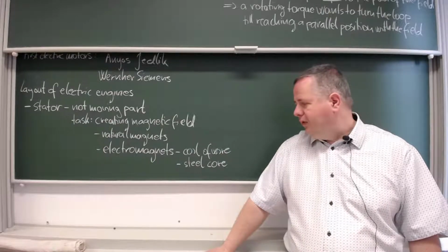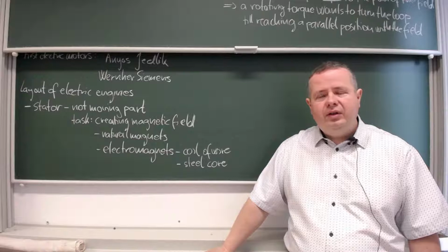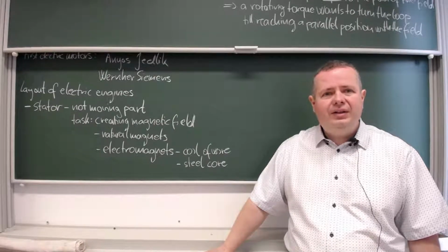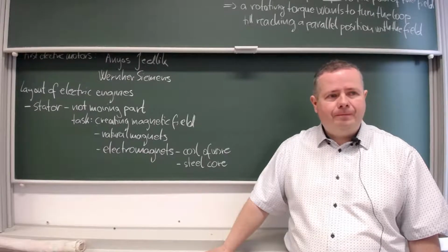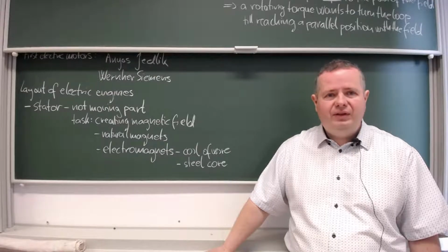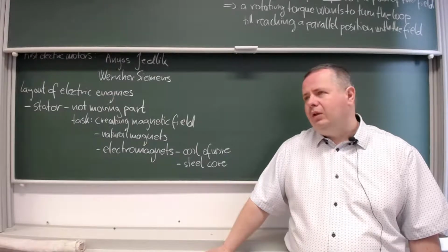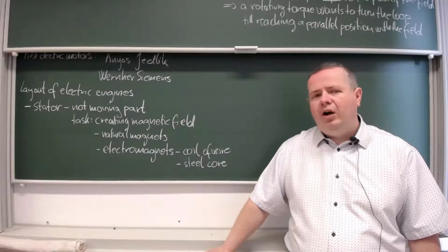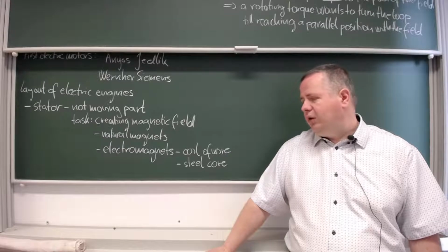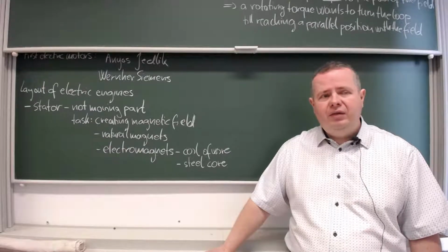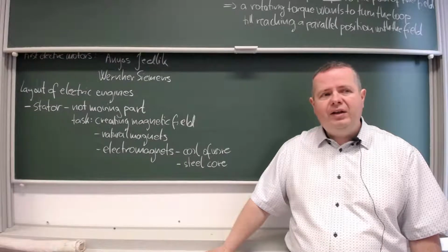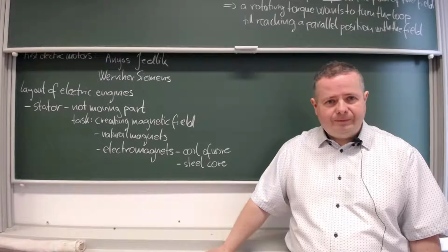The task of the steel core is to keep the magnetic field inside, to be a conductor for the magnetic field. So it's not a very hard and strong type of steel, no. It's quite soft steel which has special magnetic properties, namely very little resistance to magnetic force.